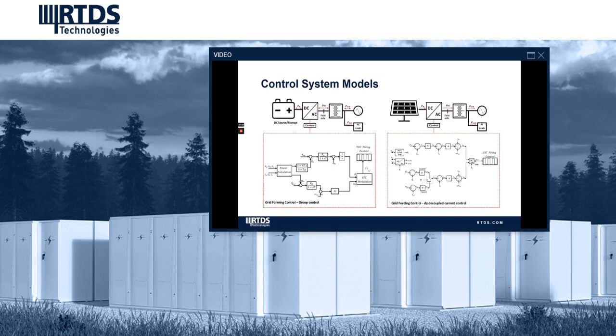The grid forming converters are modeled as voltage controlled sources. Grid forming converter controls set the grid voltage and frequency and can allow the renewable energy resource or energy storage system to form the grid in the event of a power outage or in remote power islands.